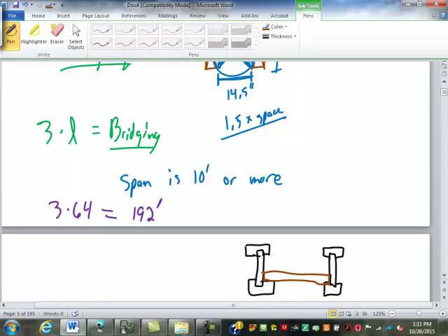If it's 16 inches on center and a 1/2 inch web, it's only 15 and a half inches, and you just put it in like that. You put a couple nails in from each direction and you're good to go. Just on one side? No, I mean like on the top and the bottom. Usually it's just the bottom is where they put them. Like I said, it is still much better to do the X.